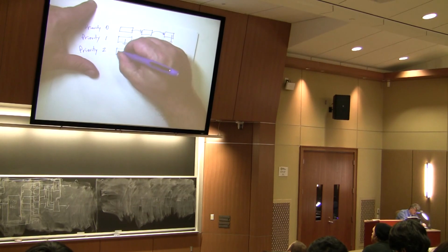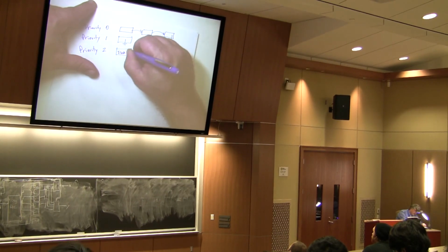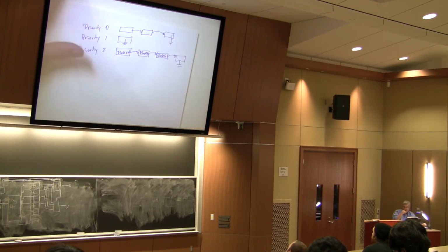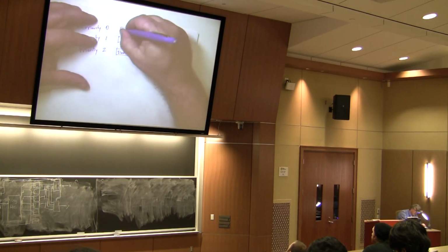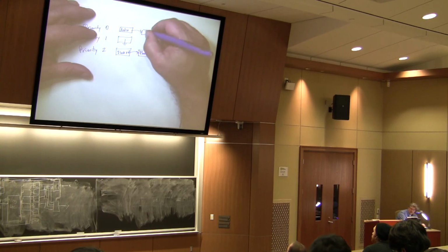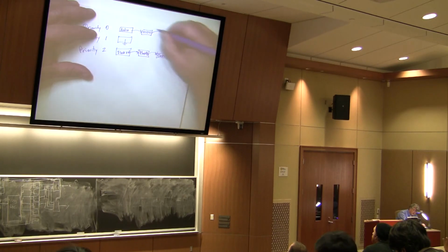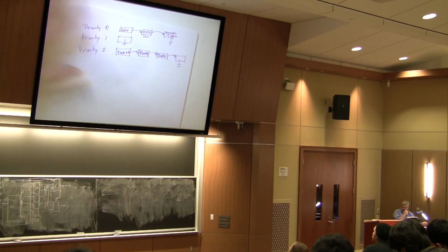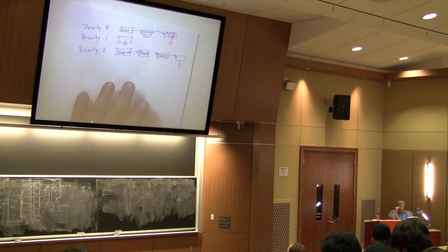And this could be the flash red, flash blue, flash green, and those aren't high priority, but this could be the audio 1 task, and this could be the RS-232 one, receive, and this could be RS-232 transmit. These are tasks that are ready to run, and you're putting them in a queue.